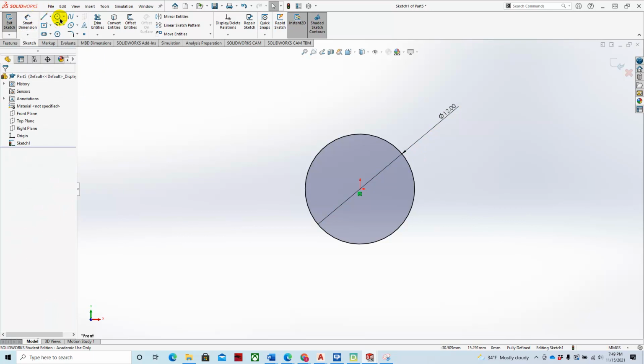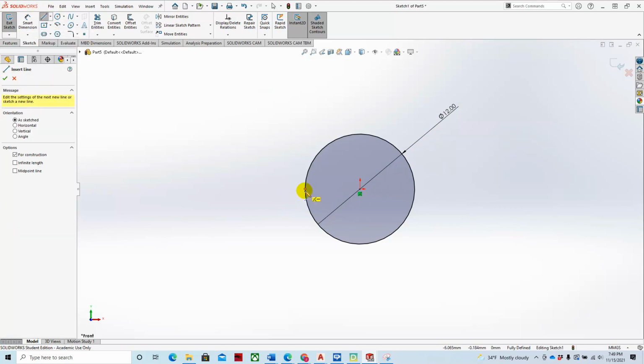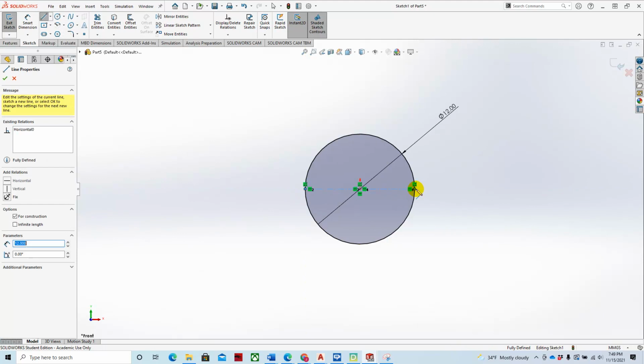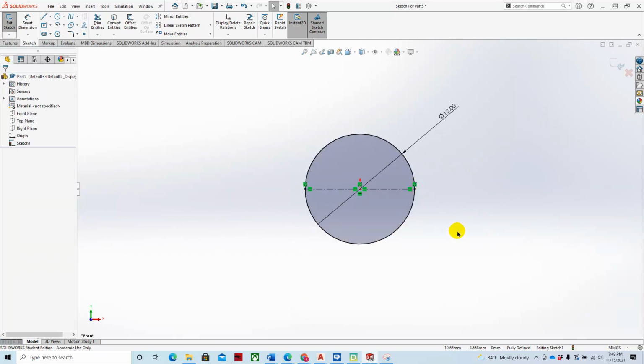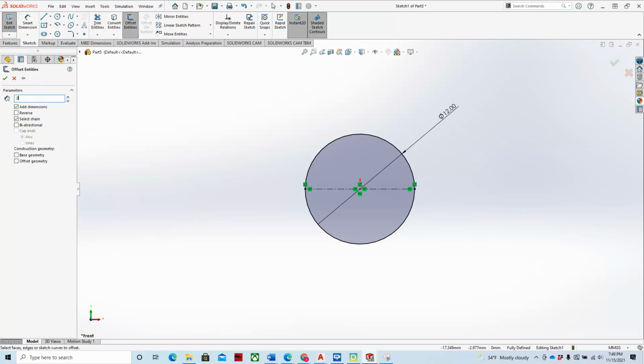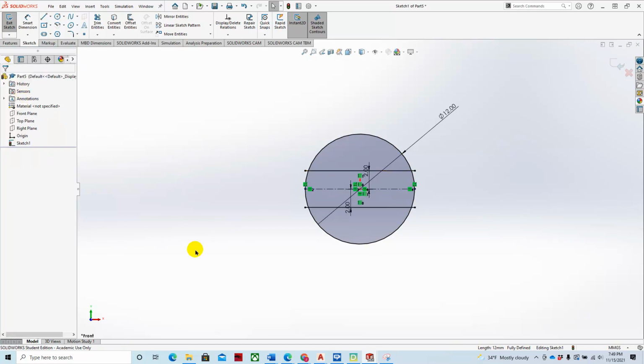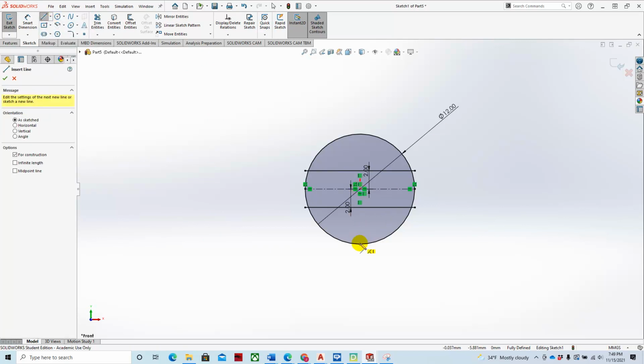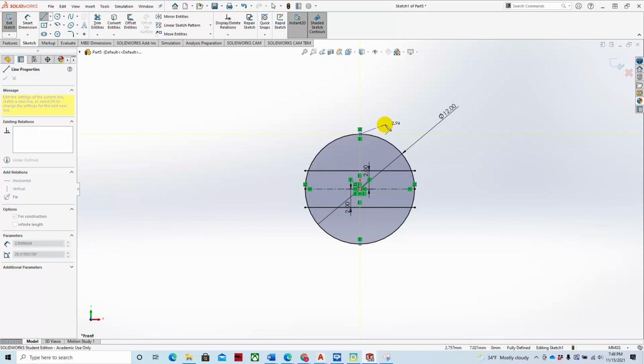And then we'll put a center line through the part. We'll offset that center line 2, and we'll do that bidirectional. We're only going to keep half of it, and then we'll make some geometry changes to that. That's going to be the through hole, and then we're going to also put another center line through the center of the part.